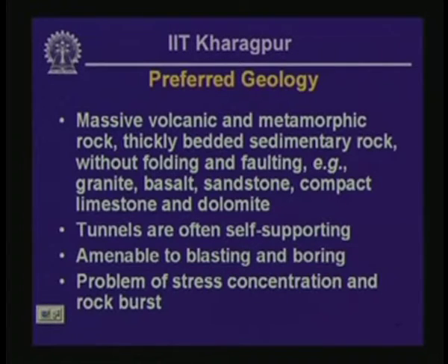Okay. So, first of all, what comes to mind is what is a preferred geological setting to construct a tunnel, and if you try to just look at the problem logically, then it would appear that if you have got a very strong mass of rock which is relatively free from joints or other structural features like shear zones or faults or other fractures, it is relatively free from bedding or lamination, then that is going to give us a very ideal situation to construct a tunnel.